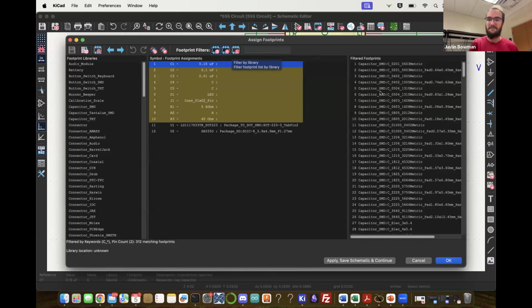So you can have a footprint that doesn't match your component if you don't click this button, which might not be useful. You can also filter by actual libraries over here, which I tend to not do. Usually clicking the 2 buttons on the left and in the middle gets you the most accurate pads that you can use. We've now filtered it by clicking these 2 buttons.